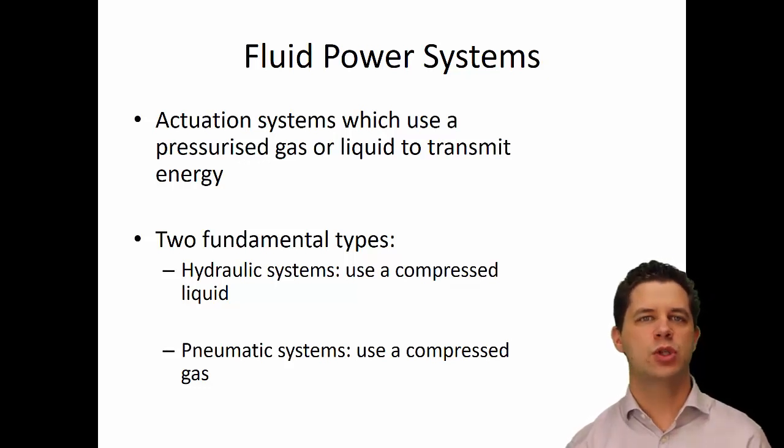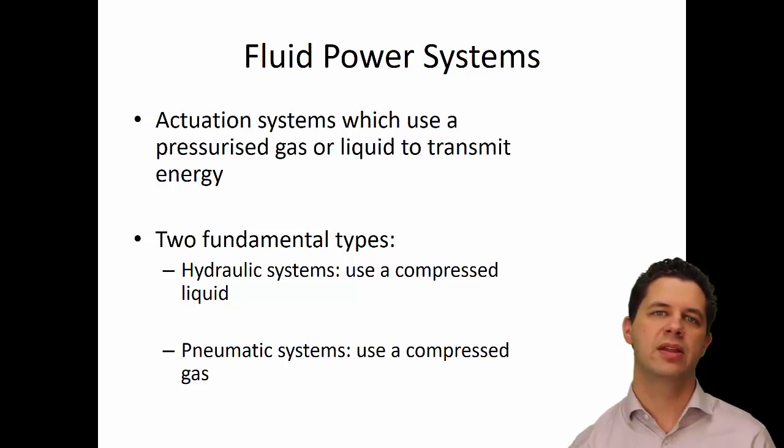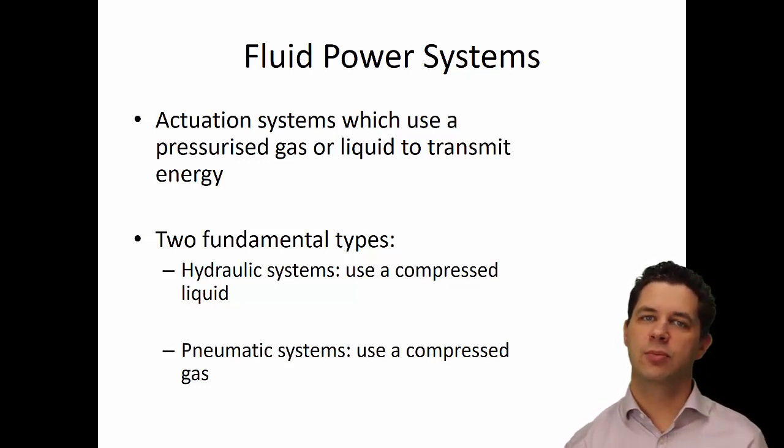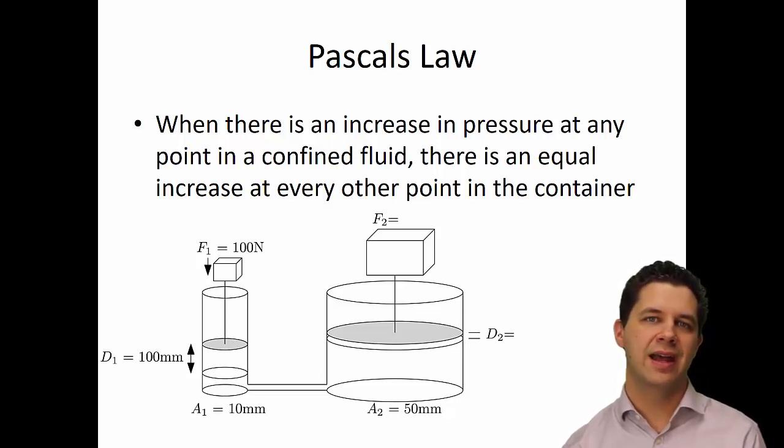And we've got two fundamental types here. We've got hydraulic systems that use a compressed liquid, like an oil or something like that. And we've got pneumatic, which use a compressed gas, typically air, to perform this sort of task. Now, one thing that these both rely on is Pascal's law. Basically, Pascal's law states that an increase in pressure at any point in a confined fluid, we have an equal increase at every other point in the container.